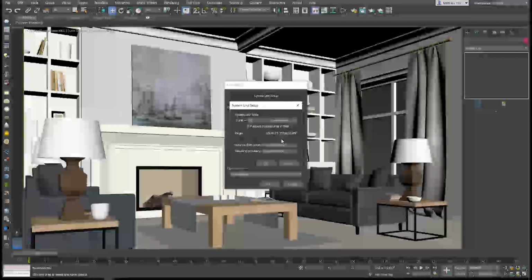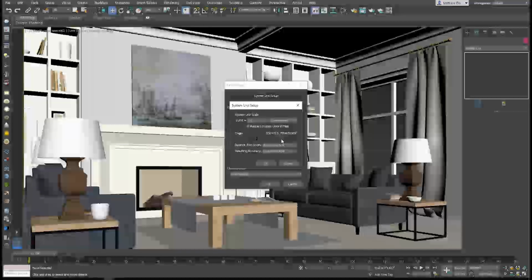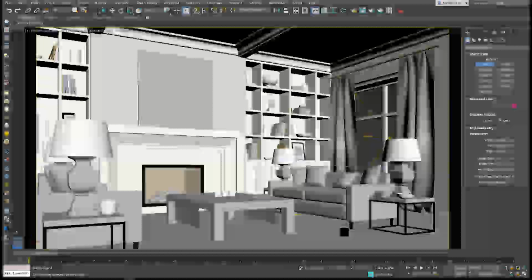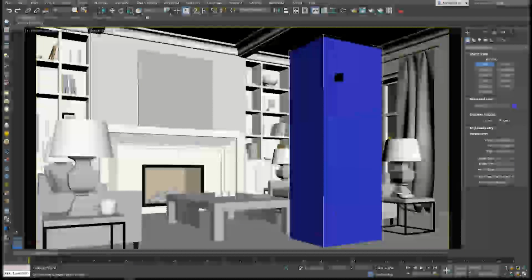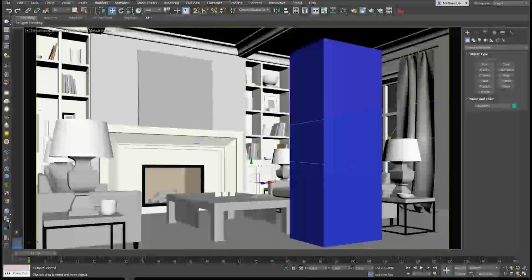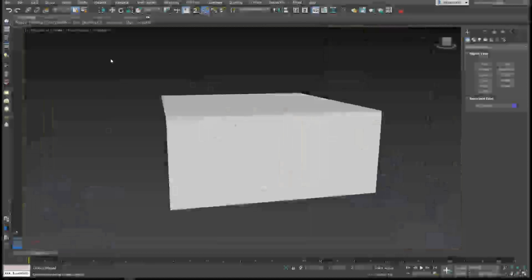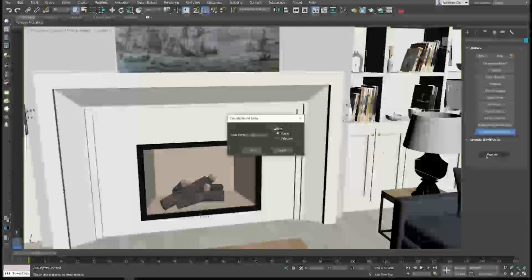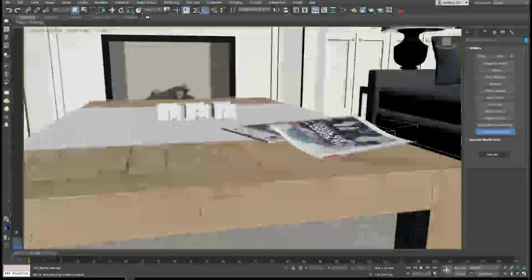scaling-related issues. One option you have is to set Max to use centimeters, then load the scene that uses another unit scale, and choose to rescale the file objects to the system unit scale. Verify everything looks good using a simple stand-in object to represent a human at roughly 175 centimeters tall. You could also try using the Rescale World Units utility in 3ds Max. Use a scaling factor of 2.5 to go from feet and inches to centimeters.